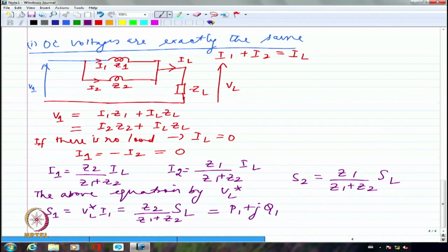Because if I increase it further, say I put two 1 kVA transformers together because I wanted to supply a 2 kVA load, at 1.5 itself maybe one of the transformers has reached its brim. You can't load it further. So if I try to increase the load further than 1.5 kVA, the transformer which has already taken 1 kVA will be overloaded in all probability.